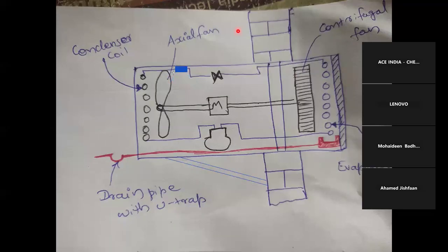The purpose of the strainer is to sieve out small dust or small rust particles along with the fluid. Why? Because these capillary tubes have a diameter ranging from 0.3 mm to 3 mm itself, isn't it? So if the dust started to enter into the capillary tube, a small clogging will happen inside the capillary tube itself. In order to prevent that, we need to implement these strainers right in front of the expansion device, right behind the expansion valve itself.